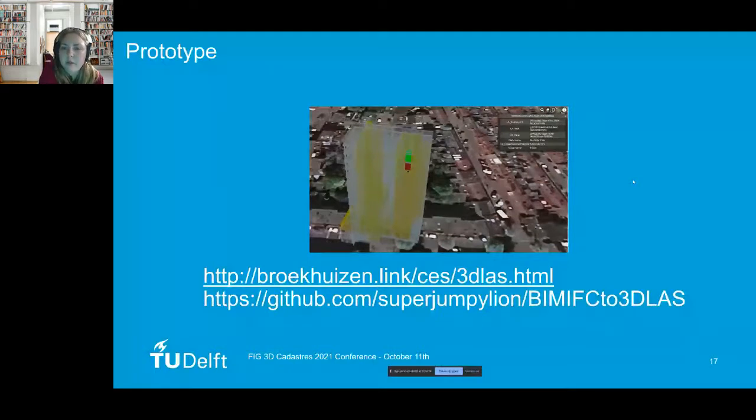Based on these findings, we have formulated some recommendations and guidelines for BIM IFC models to be designed. First of all, rooms have to be included in the BIM IFC model as IFC space. Also, they should contain a property set which includes the apartment index number, cadastral parcel number, complex number, space type, and municipality to link them to the 3D LES in the Netherlands. And also attributes for georeferencing should be included in the BIM IFC model. It is recommended that IFC4 files are used because they have better attributes which are capable of georeferencing. And for existing models, it is not necessary to enrich the IFC files with attributes complying to LoGeoRef 40.